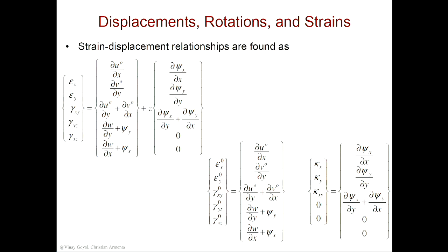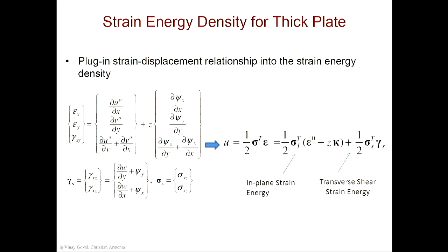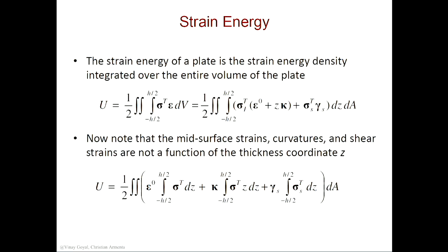Then I put them in a form that's easy to follow, because then these are mid-surface strains, and these strains represent the curvature. So I have curvatures and in-plane strains. Then I calculate strain energy density, then I calculate strain energy in the system.